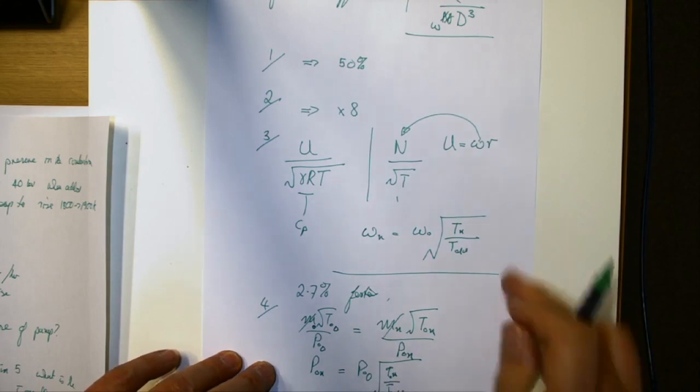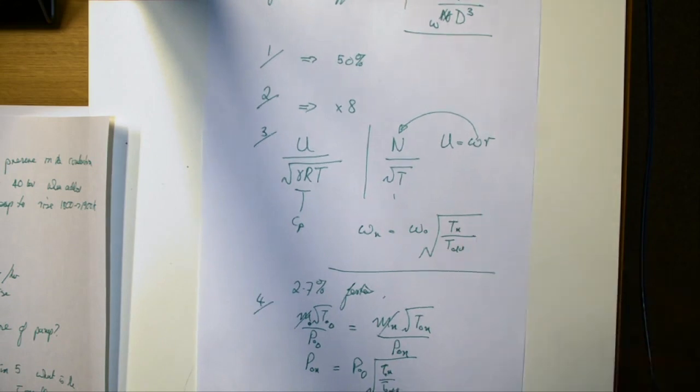Do we need to memorize these non-dimensional groups? These, yes. In general, no, but these are, from my point of view, completely prosaic. They are part of describing turbomachinery. So the N root T upon P and the N upon root T are bread and butter. I think you're talking about exams. I would expect you to know these groups. The only tricky bit about them is they're semi-dimensional. They're not actually dimensionless groups.